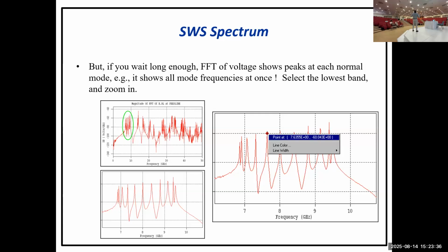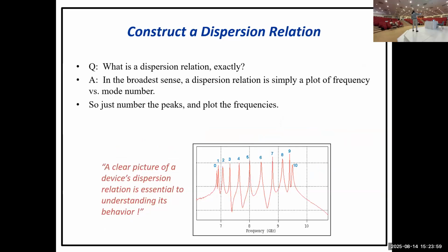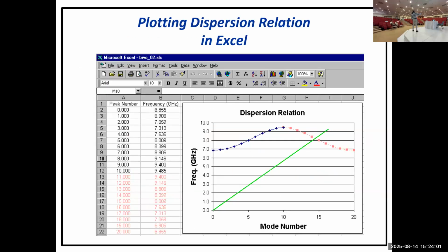Remember from the morning, for linear devices, how many resonances are you going to end up with? For magnetron it's N/2. For linear devices it's N+1. You'll see the first passband, then the second passband, and so on and so forth, and you can get the dispersion curve out of these points.